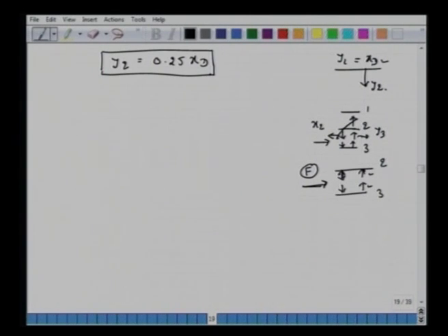Okay, y2 and x2, they are in equilibrium. y3 and x2, they will be given by the operating line. So we write down the same expressions now for y3. y3 equal to 0.81 x2 plus xt over 5.34. But again, x2, this stream is in equilibrium with this stream y2.